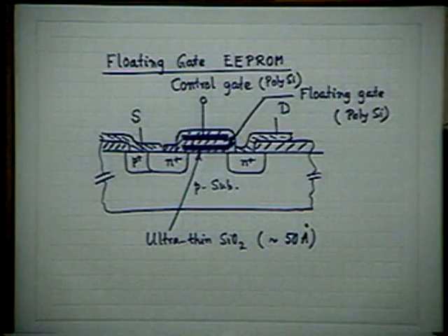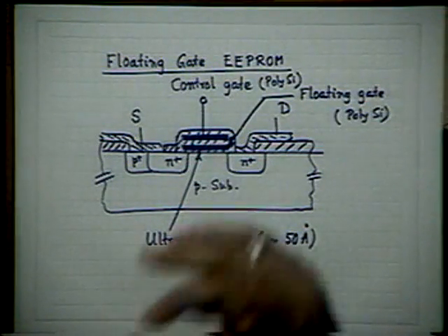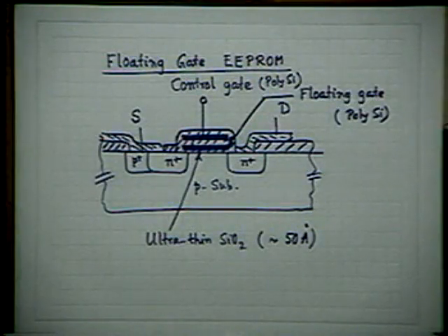And you see that after the formation of the two gates by two poly, this is called a two poly system. You know that any MOS or CMOS technology is normally described in terms of two poly, two metal, two poly, one metal, two metal, one poly, etc. This is an example. Normally in this case we have to use two poly levels, and then at least one metal or two metal. That depends on the complexity of the VLSI circuit. So this is a two poly system.